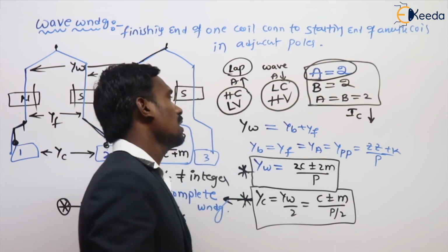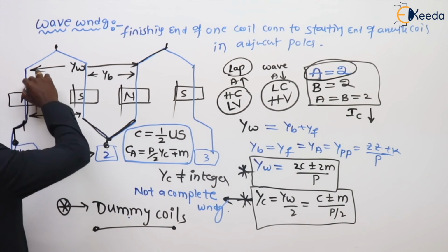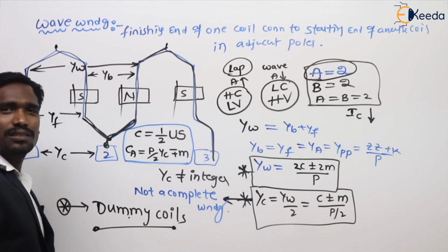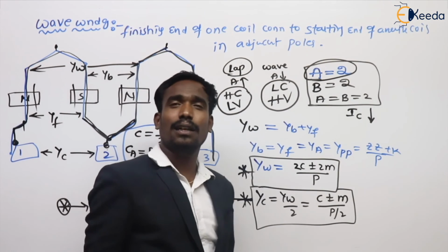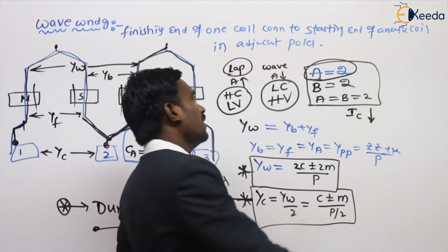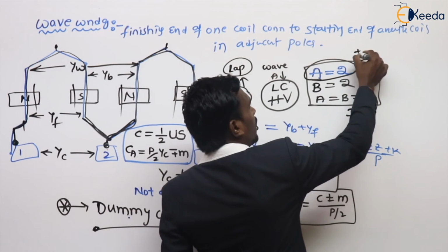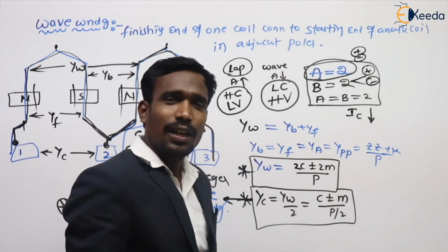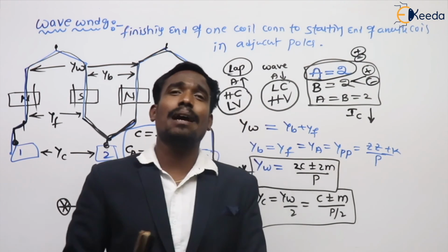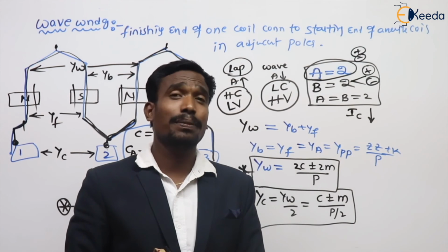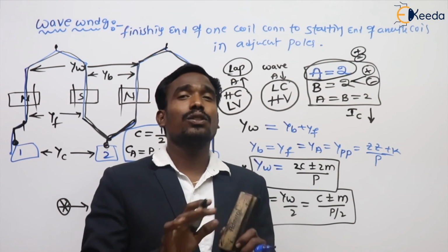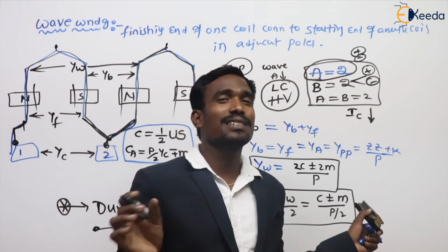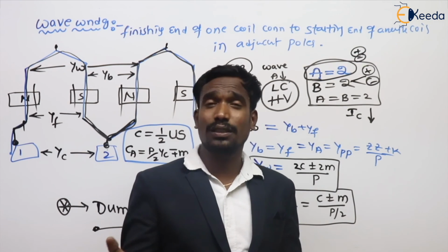And next one, generally in lap winding, every parallel path covers total number of poles. This is important. In that we have two parallel paths, one is the positive, another one is the negative. Two brushes, one is the positive, one is the negative brush. In lap winding, if any one brush is damaged, what happens, sir? If any one brush is damaged, then the total output is 0.